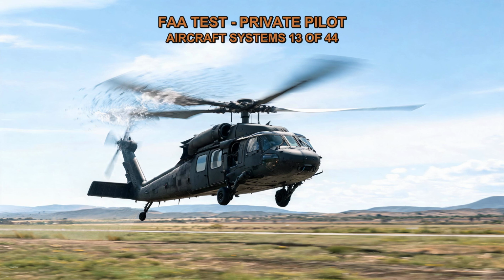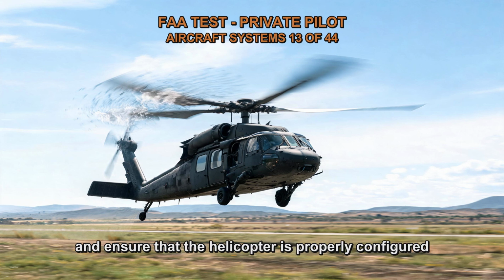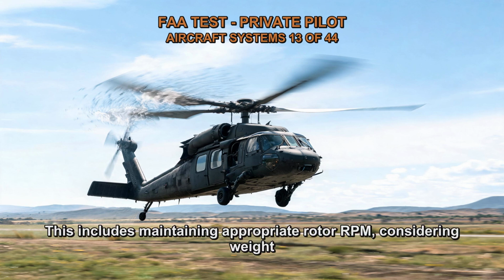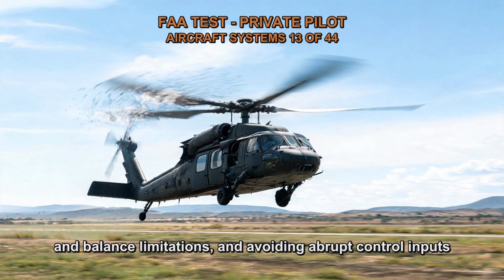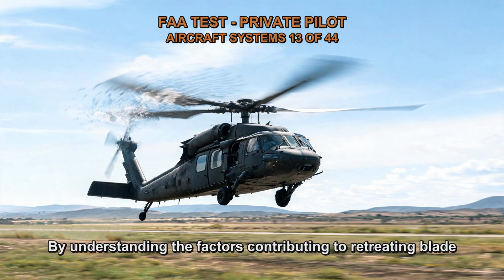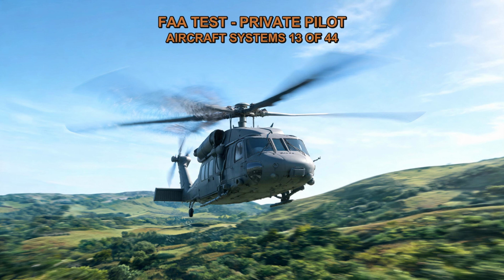To mitigate the risk of retreating blade stall, pilots must operate within the established airspeed limitations and ensure that the helicopter is properly configured for the given flight conditions. This includes maintaining appropriate rotor RPM, considering weight and balance limitations, and avoiding abrupt control inputs or maneuvers that could induce high angles of attack on the retreating blade. By understanding the factors contributing to retreating blade stall and adhering to safe operating practices, pilots can effectively manage this limitation and maintain safe flight operations.